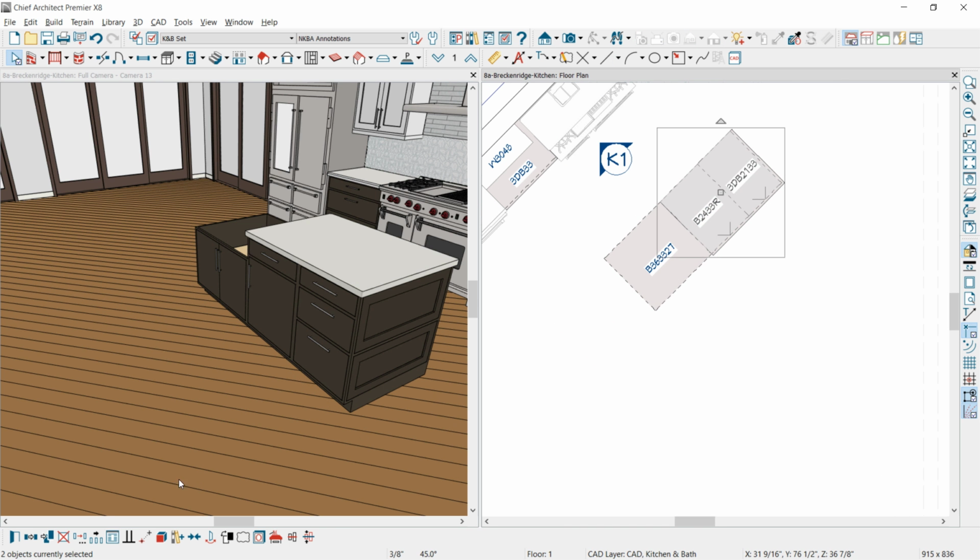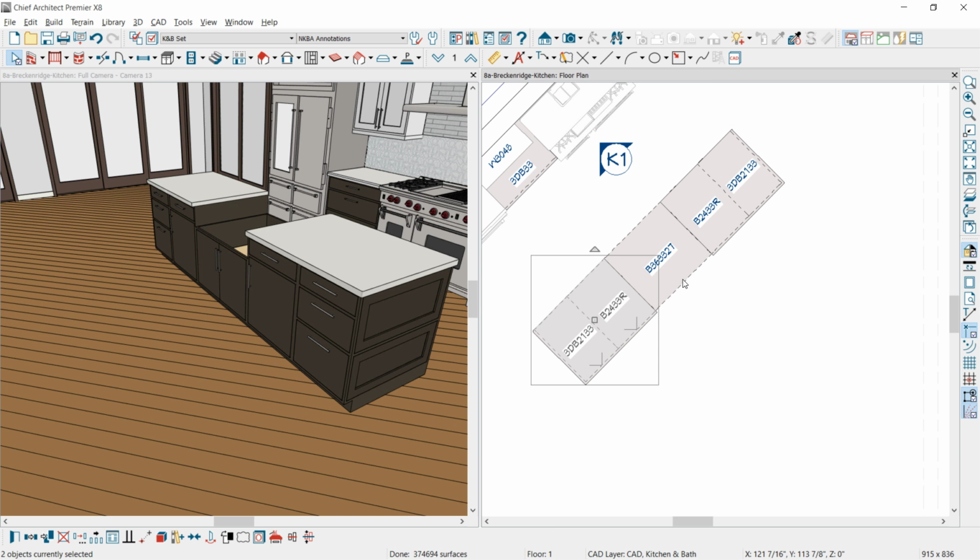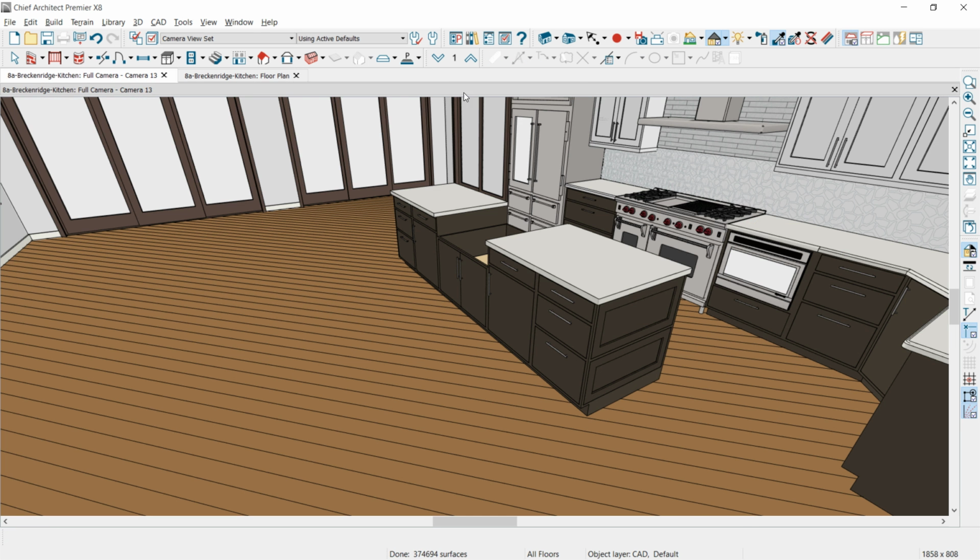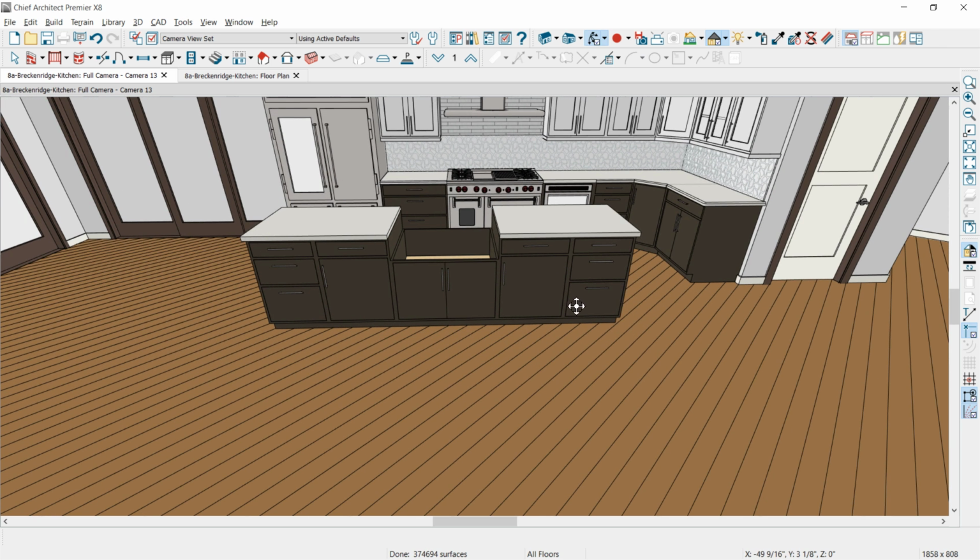I'm just going to grab these 2 cabinets, and I'm going to use the copy and reflect about you'll find in the lower menu, and then we'll just rotate that around the other cabinets. Again, I'm building this island in reverse. And let's go in and maximize our 3D view and change back to the orbit. And now I want to grab an apron sink, place that, and then we'll do the custom countertop on the back side.